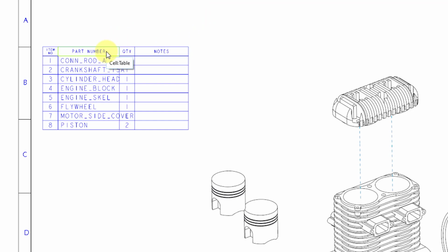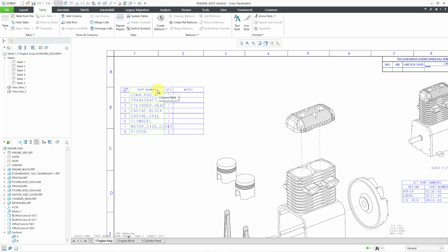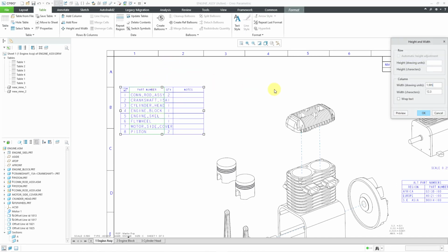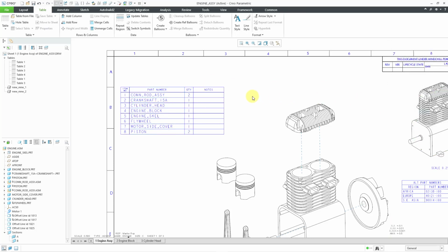But my first column is way too short. Let me tap right, and then when it highlights, I will left click to select it, and then go to column width, and let's crank up the number of characters to 20, and then click on the OK button. I see that my skeleton is listed in here. I can remove that from the repeat region.